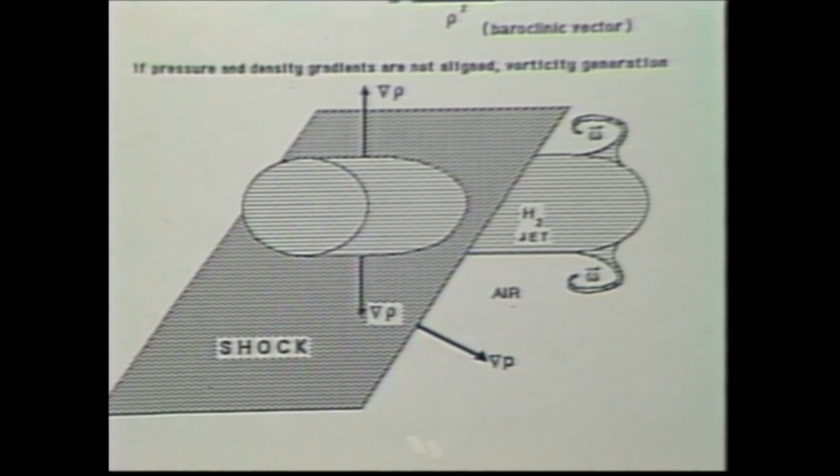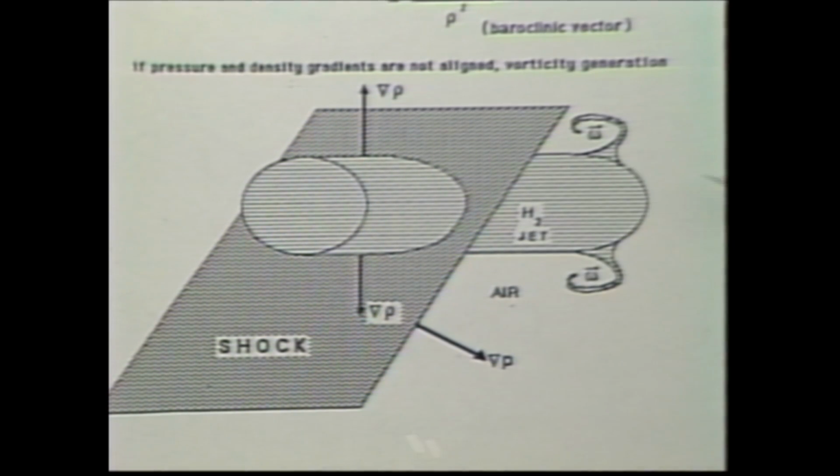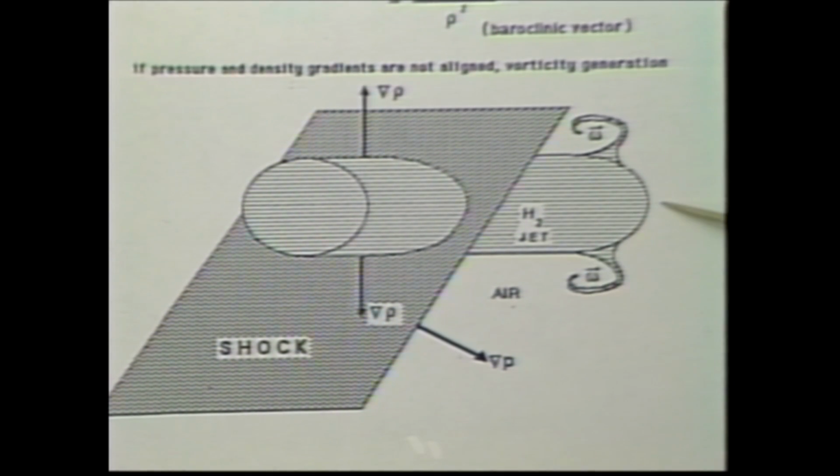What are the problems with that? Well, one problem is, of course, you need a shock. And shocks have losses associated with them. So this becomes an engineering game. Picking a shock which is strong enough to induce the vorticity and induce the mixing, but making sure it's a shock which is weak enough that you don't suffer strong total pressure losses and thus ruin the performance of the engine. Again, this is by no means the only concept.